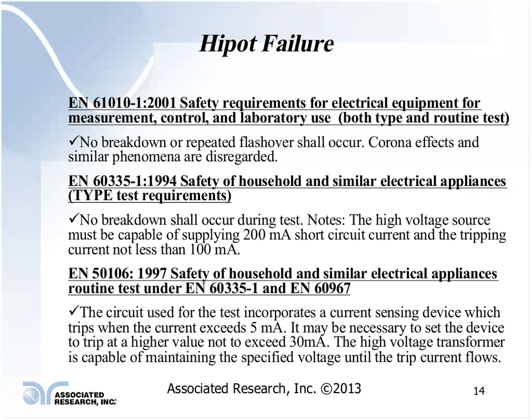Typically, with the testers that are used in most production environments, as long as you have an instrument that has a regulated output and you're monitoring the voltage on the output, in most cases you can use these testers with a smaller current capacity. Testers today are much safer than they were years ago, because a lot of them have multiple trip devices.